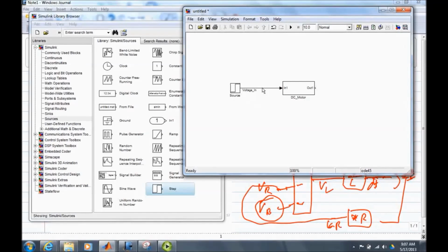Now I can label that signal. It's always a good idea to label every signal, even if there's some redundancy in the labels, because believe me, when you come back 6 months from now, you look at that and say, what was that for? You just won't remember. And labeling everything just makes it so much easier to follow, so much easier to debug.